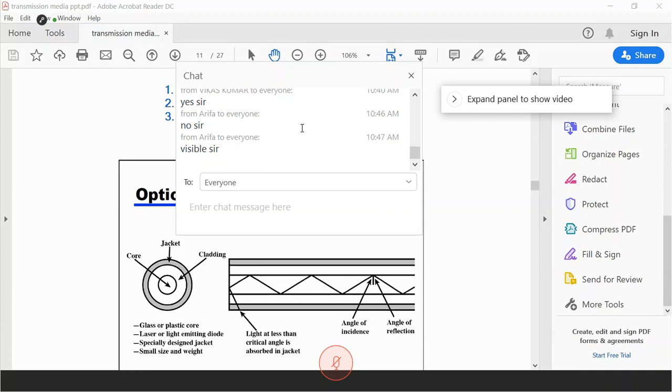But then you will say, sir, we see a fiber moving across our department that is thick. The core is of 50 microns. Then you have cladding and jacket to protect it. That makes it a bit thicker. And if you talk about single mode fiber, which I have drawn here, its core is much less than our strand of hair. That is of the order of 8 to 10 microns.